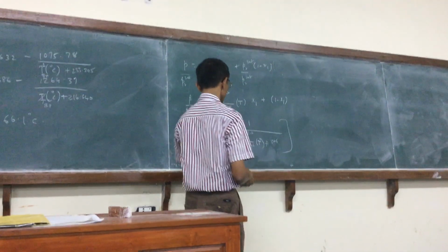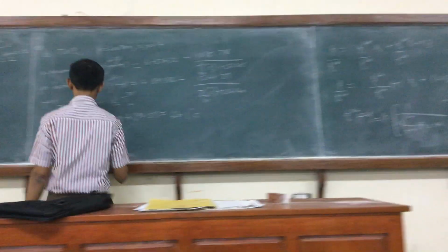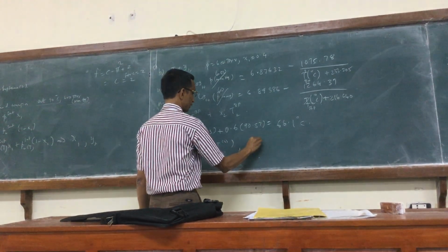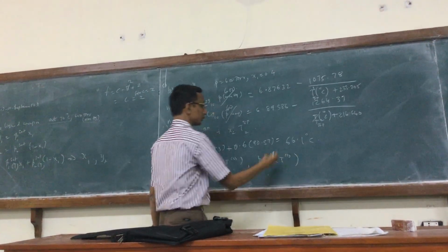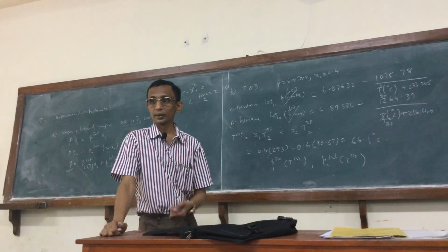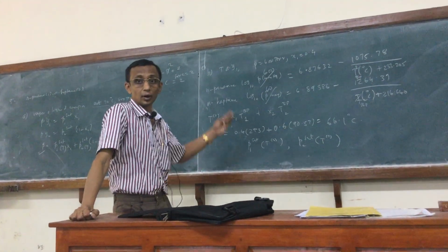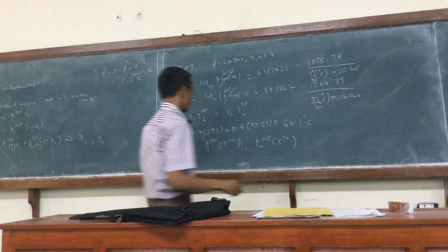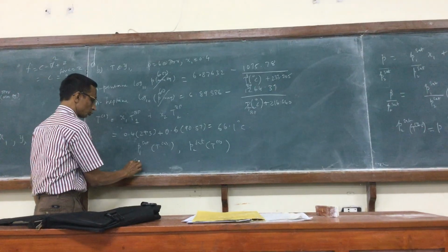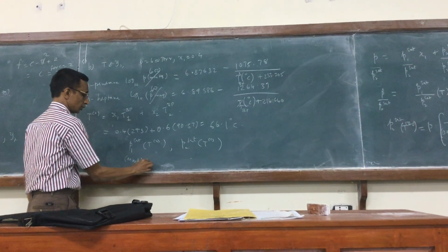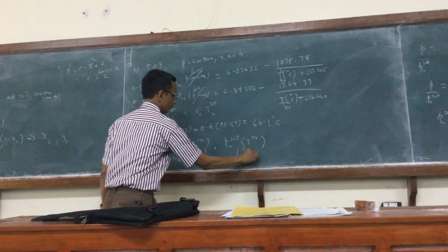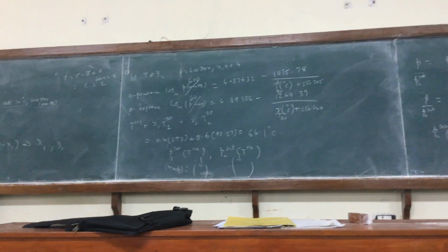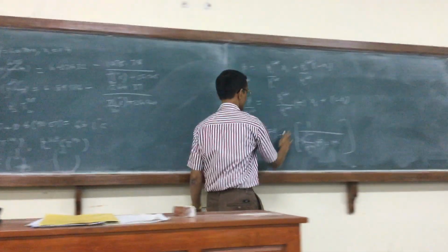First thing I have to now do is to calculate the saturation pressures, keeping T in degrees centigrade, because this is in logarithm to the base 10. So let's see if we can calculate it correctly. So P1 sat at T0, in all we use mmHg. P1 sat and P2 sat, that's what I need to substitute into this equation. P is 600.